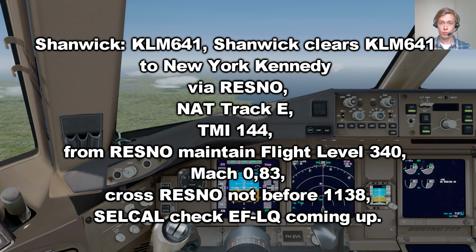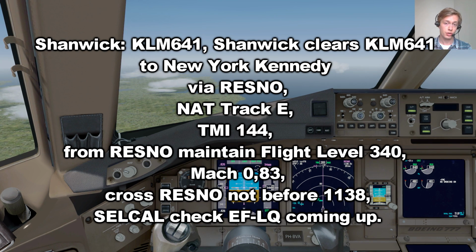So in this stage you have to wait a little bit with the reply, and just make sure you have written down all the information. At this stage the controller is going to actually send the SELCAL code, and you just have to make sure in vPilot that you receive that message. And as you have noticed, the controller gave us a restriction. We have to cross RESNO not before 1138 Zulu, and I'm going to show you in a minute in the FMC how to do this.